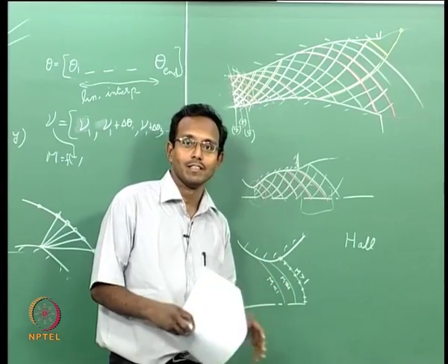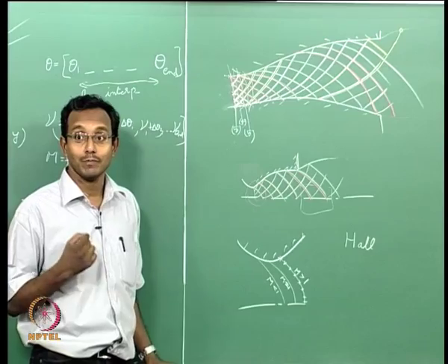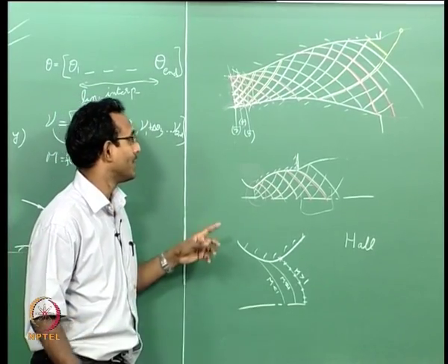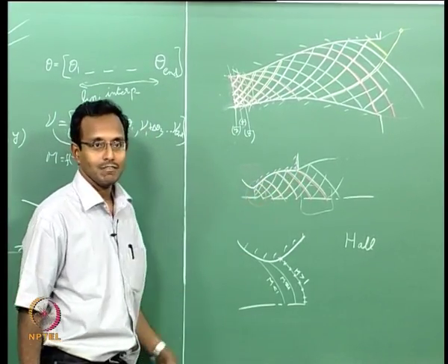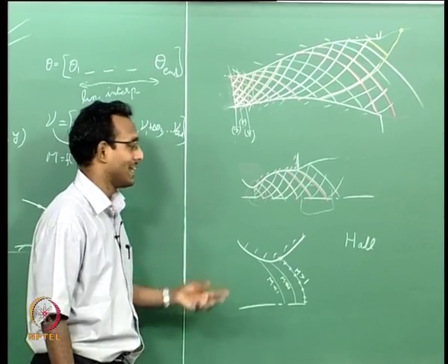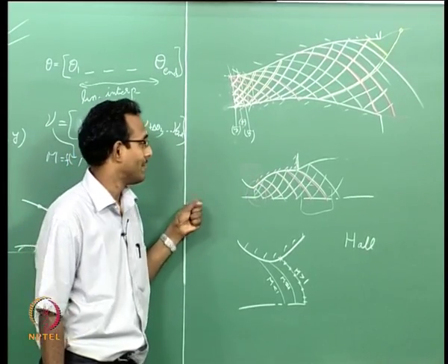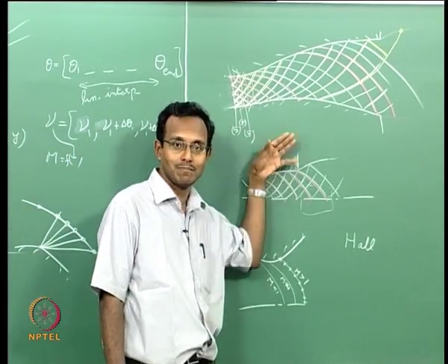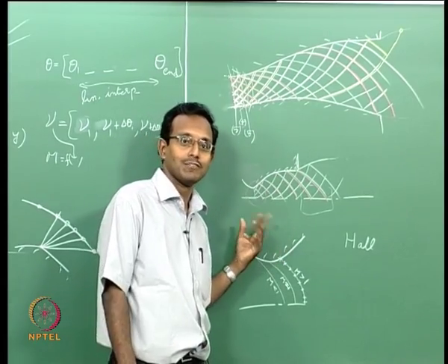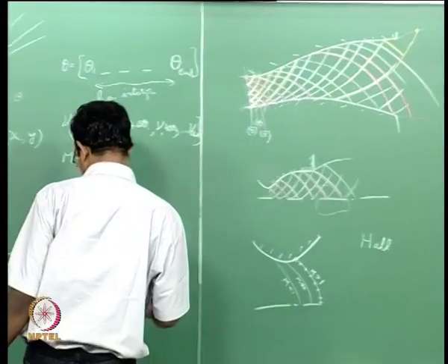But the main reason why method of characteristics became famous was because of its ability to create nozzle shapes with whatever exit flow conditions we want. Typically we wanted uniform flow because we want to create supersonic tunnels where the Mach number is exactly the same all through. That is the idea of this. So, we will look at how we can make nozzles.